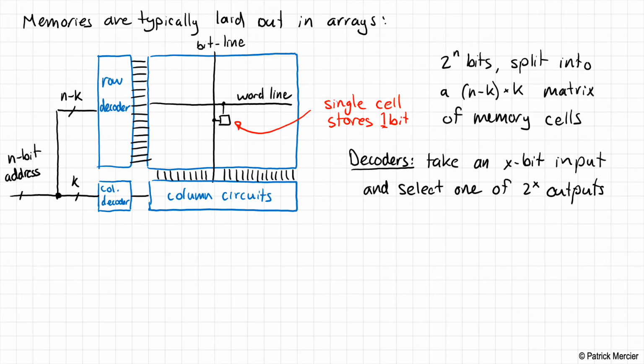So we take our n-bit digital word, we insert it into our decoder, and that will activate one of those 2 to the n lines at the output of the decoder. In that example, we were only looking at the row, but in practice, this happens for the row and for the column. So that's for a decoder.